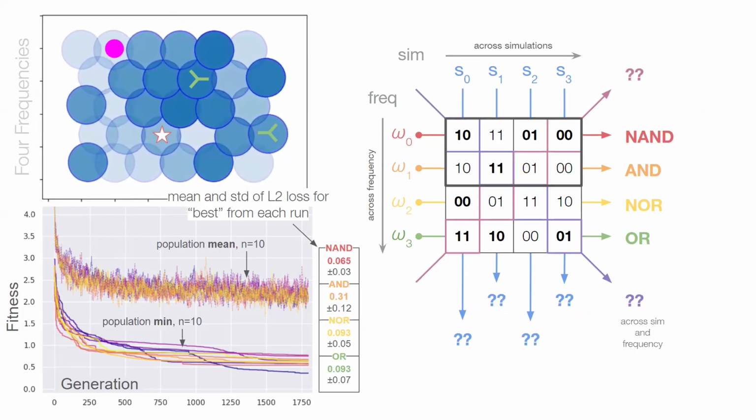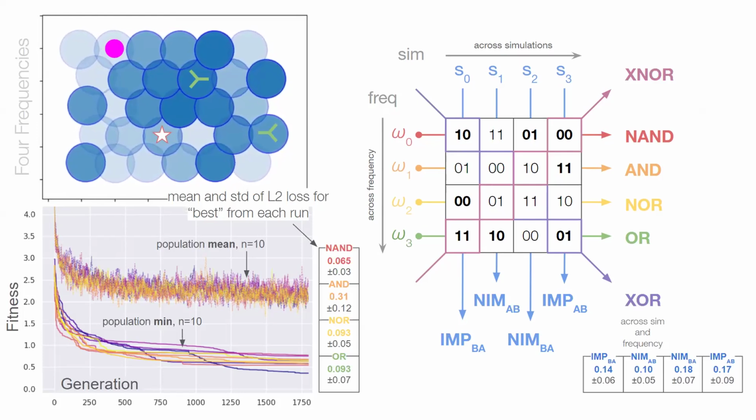So this requires a very precise ordering of this input matrix, which means that if you repeat any of the rows, then you're not going to define a parallel gate down any of the columns. That doesn't mean necessarily you're going to corrupt the ability to compute the evolved logic gates. It just means you're not going to get the parallel gates. So what you could do is you could look at all possible permutations of this matrix and see if there are synergies or interferences between these driving frequencies that are used to compute the evolved logic gates. And that's something that we've done internally, but it's not the focus of this work. Instead, we're concerned with those matrices where you do produce these parallel logic gates.